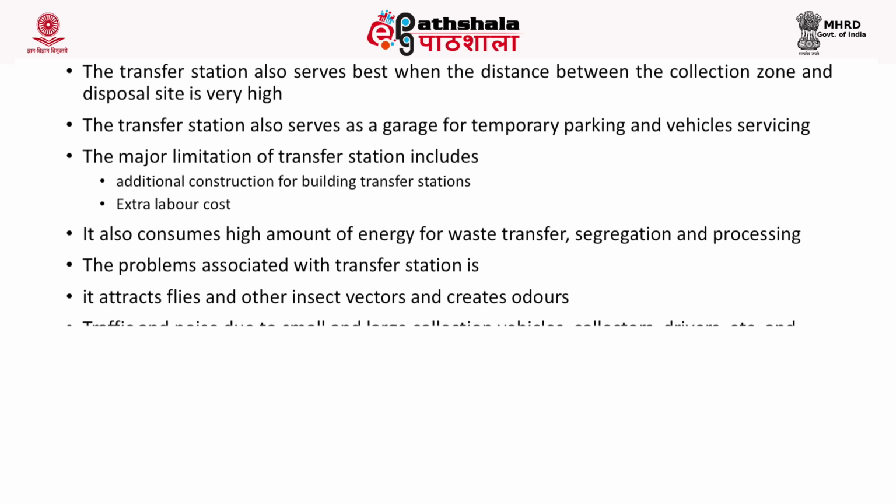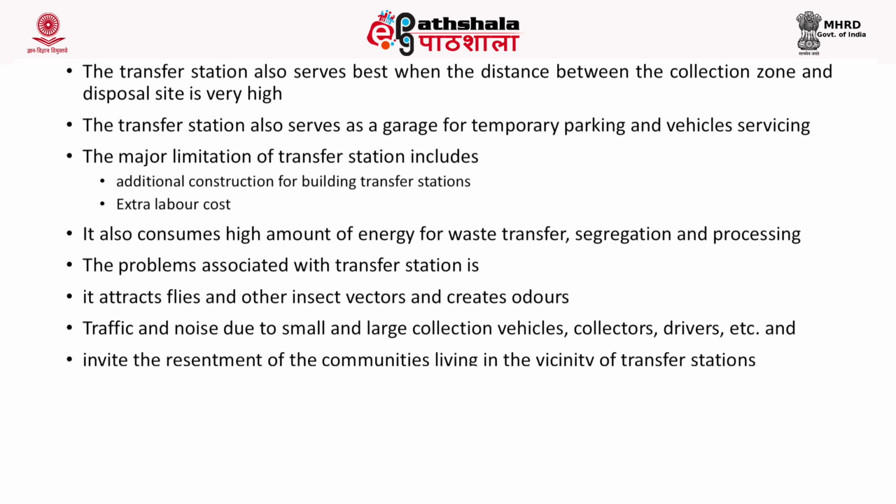Now, you have two main limitations for the transfer station, that is, it involves extra labor and additional construction cost for building it. It also consumes a high amount of energy for waste transfer, segregation and processing.